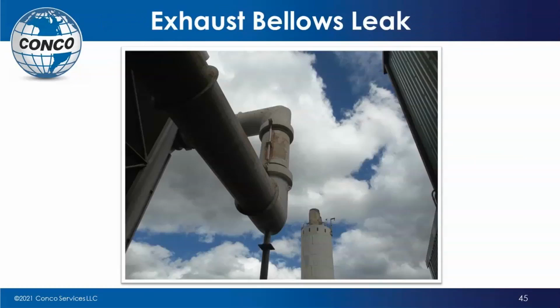Exhaust bellows leak, of course, it's out away from the ACC, more difficult to get to, but this is an area that we've got to get up and take a look at. And so in many instances, the exhaust bellows is an area that leaks.